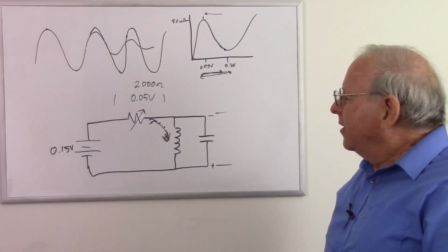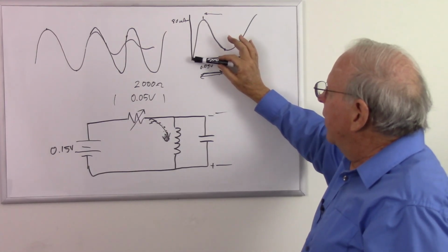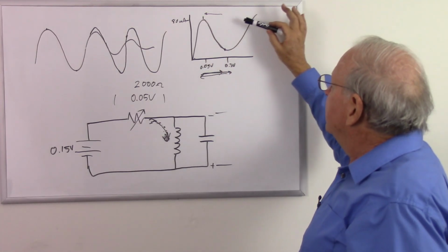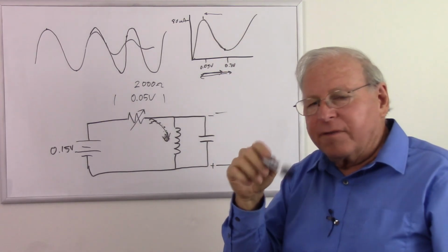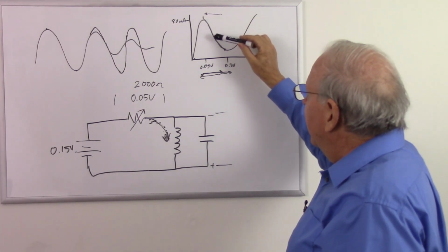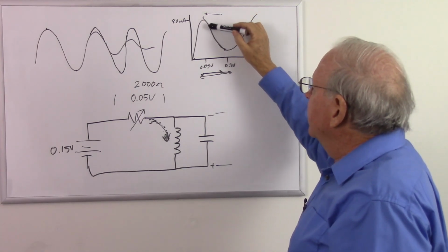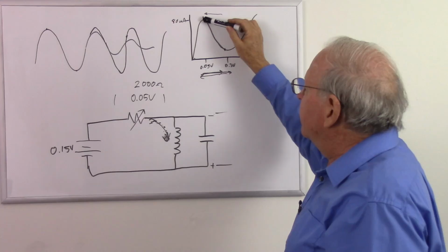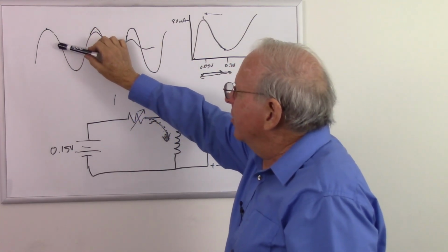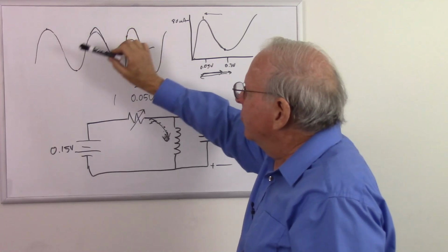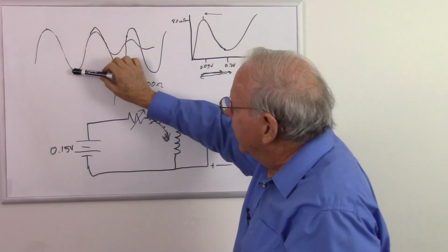we want it. So in the relaxation oscillator, we find that the tunnel diode is first over in this region, jumps over to this region, drops down to there, jumps over to there. But in the sine wave oscillator, we find that it stays in the negative resistance region. So high resistance, low resistance, high resistance, low resistance, perfectly in sync. High resistance means going to be high current, pushes this voltage up. Low current allows that to go down.